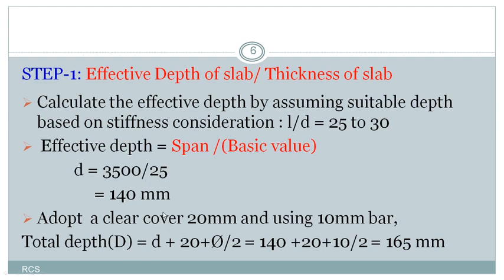According to that you have to calculate the maximum you can provide. You will not provide more than 12 mm bars in a slab, right? So based on that criterion I am using 10 mm bars. From that I can calculate the total depth.